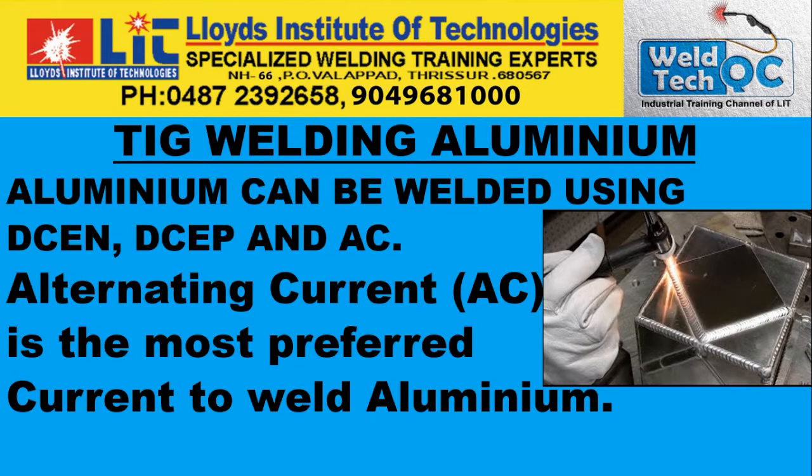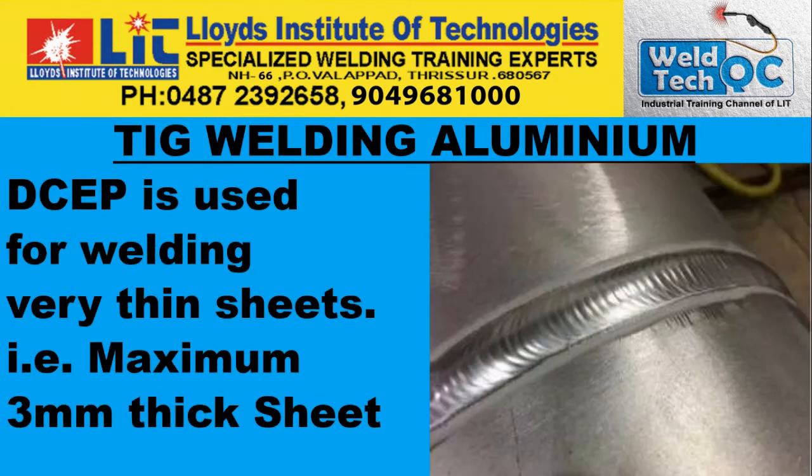Aluminum can be welded using direct current electrode negative, that is straight polarity, DCEP, that is direct current electrode positive, reverse polarity, and alternating current. Alternating current, that is AC, is the most preferred current to weld aluminum. DCEP is used for welding very thin sheets, maximum up to 3 mm thickness.